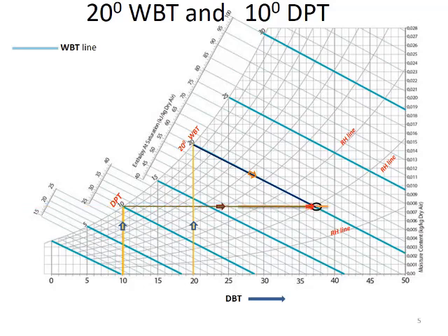So next is specific humidity omega. From that point move towards right. So it is between 0.007 and 0.008, maybe 0.0078 because it is very close to 0.008. Next, if you want to find out dry bulb temperature or DBT, it is very simple, directly come down, because when a DBT is given, what you used to do, you used to go up to locate that point.